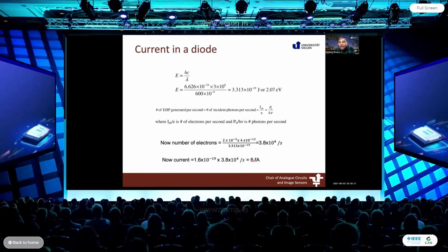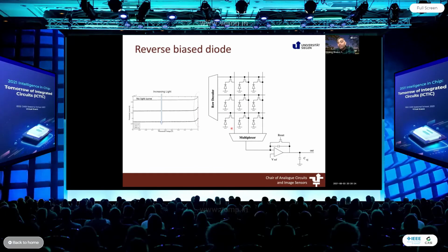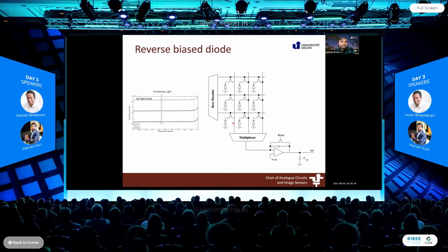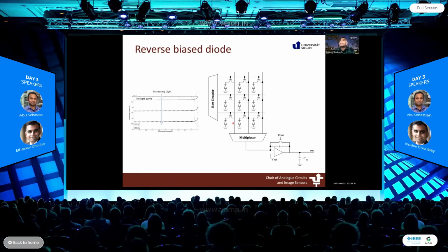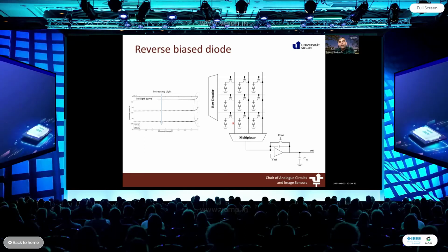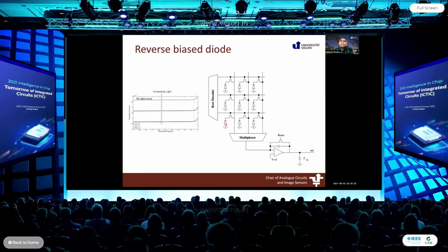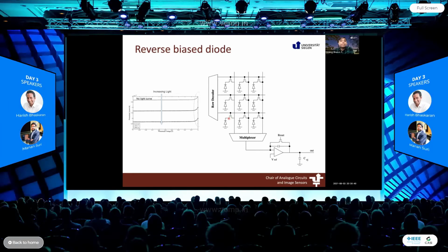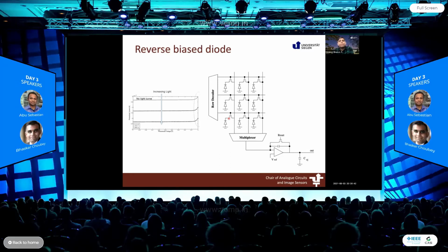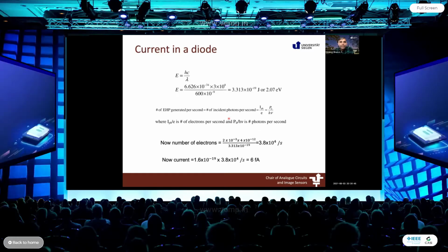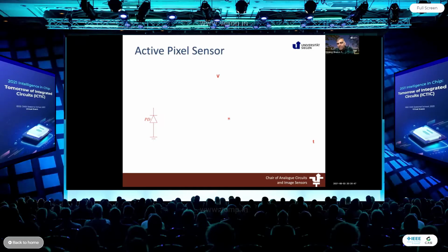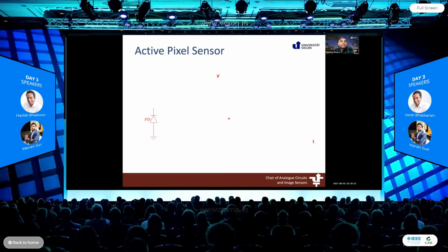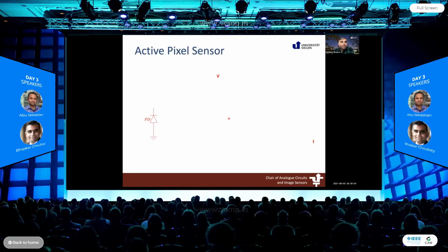We cannot design just a diode array, as I just talked to you guys. So we need to do something more inside the pixel to buffer that very small amount of 6 femtoampere current. Which means our simple circuit, which had just a diode and a resistor and a switch, is not good enough for imaging fast-moving scenes or even moving typical video. So we ended up designing a pixel which is called an active pixel sensor, and you would see 3 transistor or 4 transistor implementations.